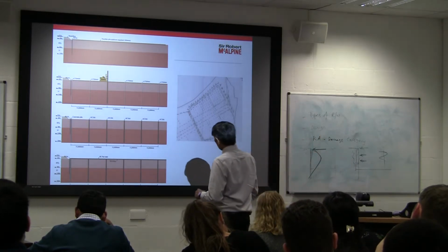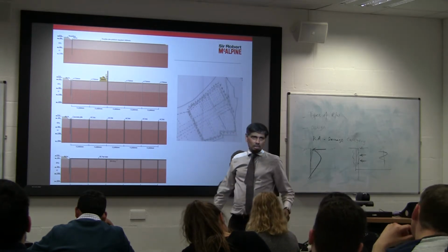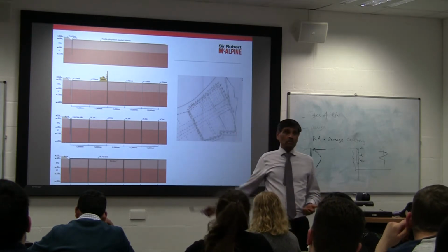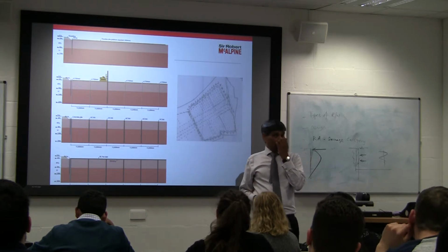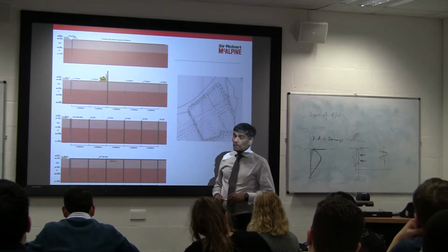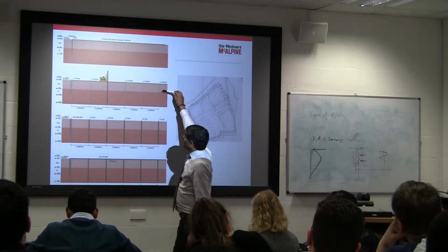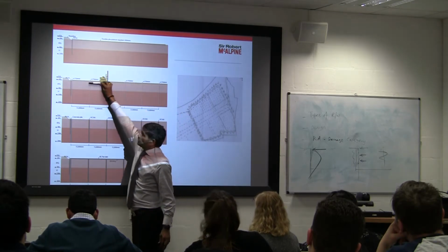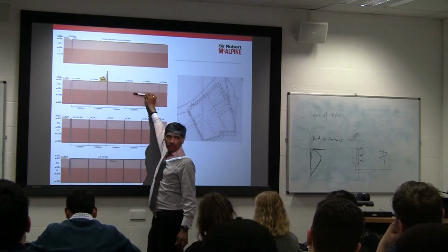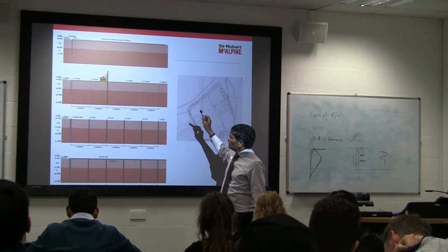Now what happens here is that if you start excavating all this, you can imagine 500 by 500 by about 10 meters, a massive amount of stuff coming, very close to the airport, restricted by the number of lorries, which is a very, very slow dig. So what we normally propose in that sort of scenario is we start first with piling, that's at your ground level. So we'll do the piling at regular grids, to tie up with the column spacings of the grid.